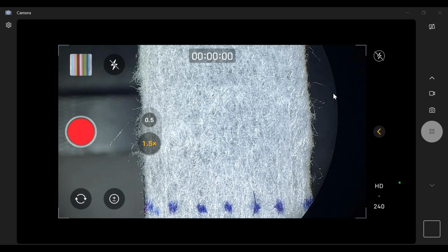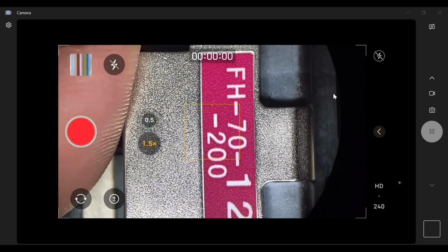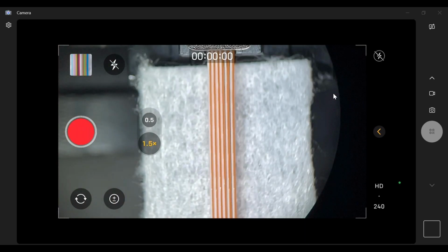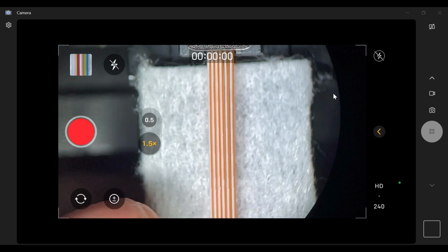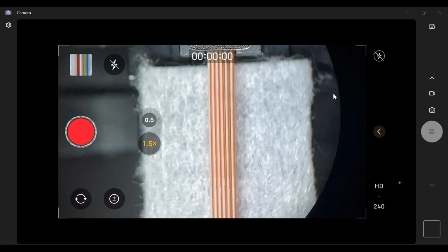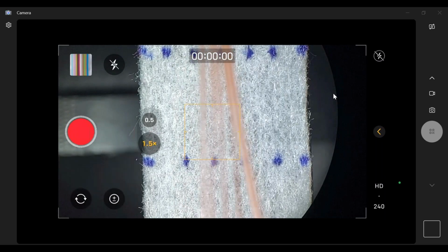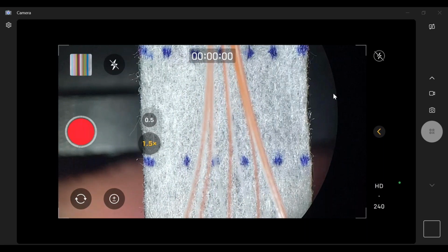I'm going to look at another supplier's material. This is 200 micron, and what we have installed is the F870-12-200. You'll notice that the width, even though it's 12 fibers, the width is a lot less. The standard width is about 3 millimeters. This particular width is about 2.5, excuse me, somewhere around 2.8, I'm sorry. And as I separate this, you can see this ribbon and its tack pattern associated with this particular ribbon.